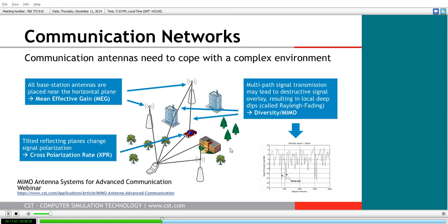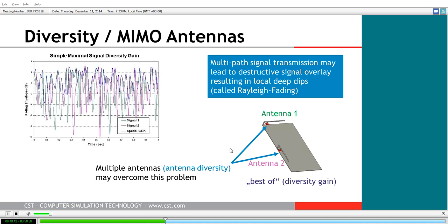Of course, that's just a path consideration, but there's also polarization decay rates as well that can individually be accounted for in models as well. The way to combat this type of fading that can occur, what's called multipath or Rayleigh fading from these multiple paths, is to introduce diversity into your antenna design. This is the so-called multiple input, multiple output antennas. So you can see here just a very, very simple MIMO antenna where there's a bit of spatial diversity as well as a polarization shift for this pair of PIFA antennas. And you can see in the resulting received signal, because we have these two relatively decorrelated signals, when one antenna is subject to a fairly large path fading dip, the other antenna is not, because it has low correlation. And as a result, for the signal that we actually receive, we can opt between the best of the pair, and we get an effective gain from this diversity.